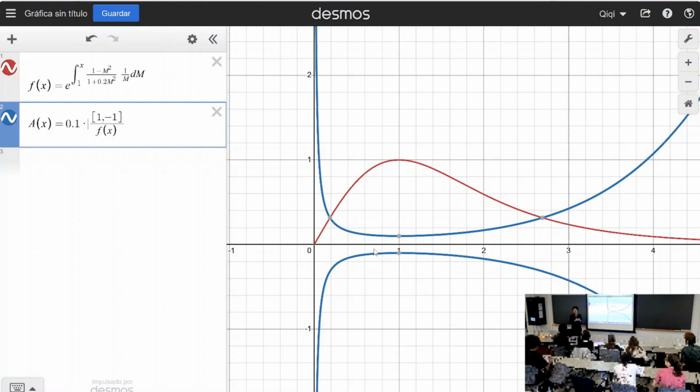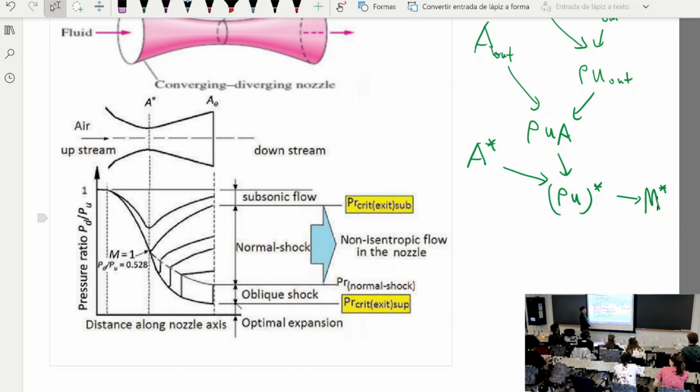Okay. All right. So these are the subsequent cases. For all not purely subsonic cases, the throat is choked, which means the throat is at Mach 1. Okay? Everything that happens upstream will be exactly the same. As long as the throat reaches Mach 1, the converging part of the nozzle doesn't change anymore. No matter how you change the downstream pressure, nothing changes upstream of the throat.